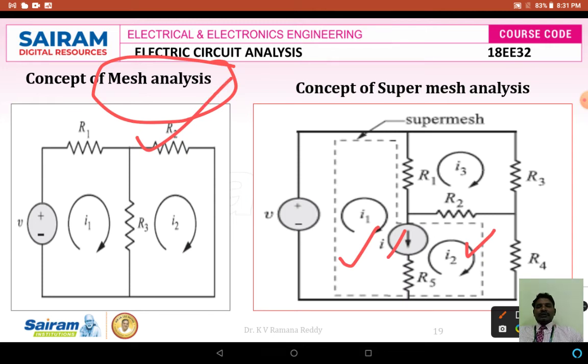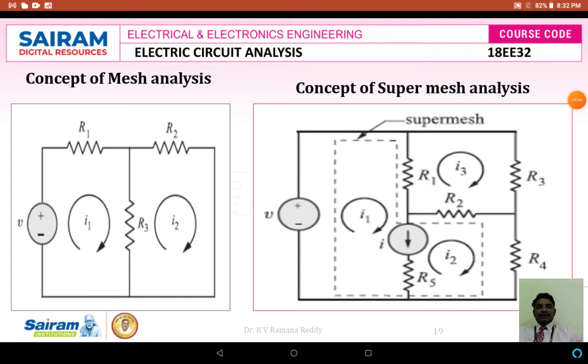To overcome that difficulty, we now approach a technique called supermesh analysis. How do we apply supermesh analysis to find the solution? Here we have to write a current equation, that is the difference of these two mesh currents, I1 and I2.